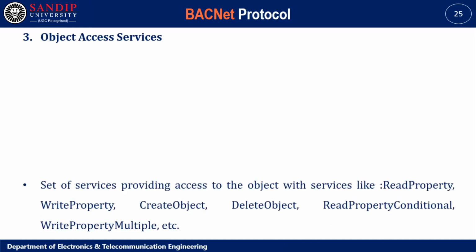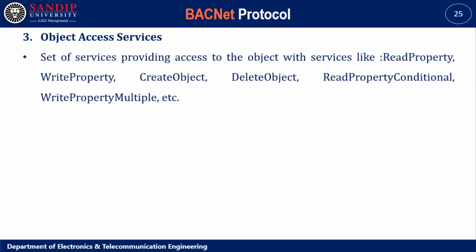Object access services. Set of services providing access to the object with services like read property, write property, create object, delete object, read property conditional, write property multiple, etc. Remote device management services.